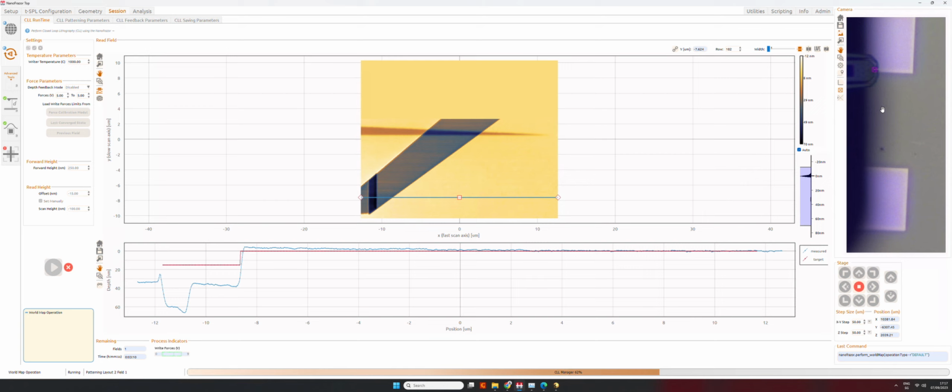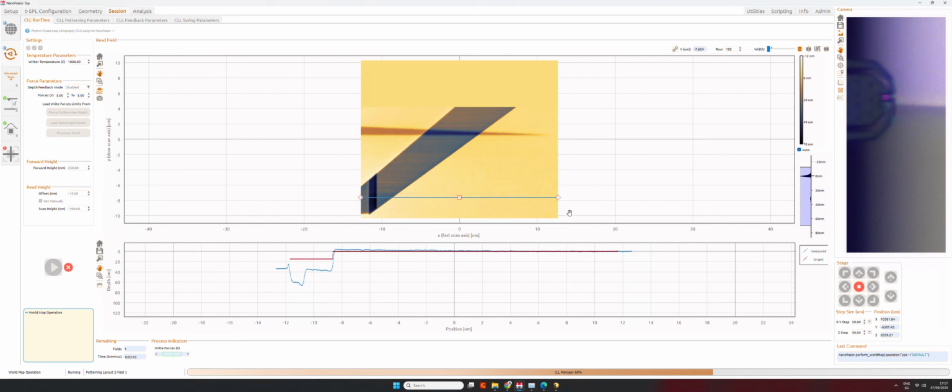So in the meantime, let's check our patterning. Here we are patterning on top of the contact pad, and we have some artifacts because of the flattening issues. We are flattening on the right, where the Nanofrazor software thinks that the right side of the image is at the same height, but of course it's not, because this is around 30 nanometers and the bottom part is at 0.